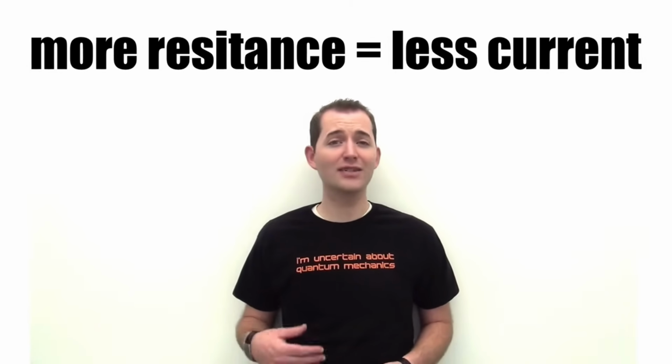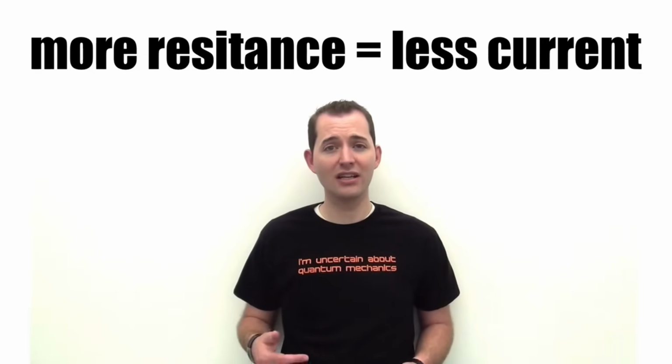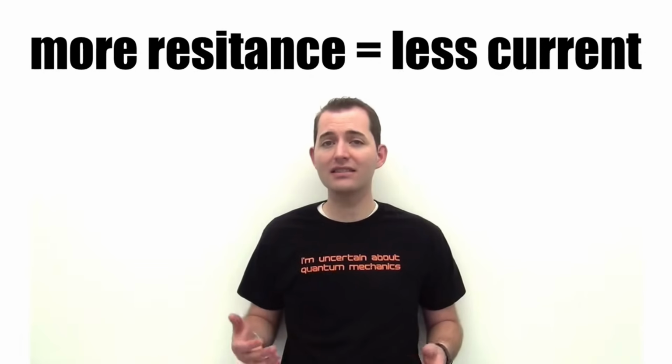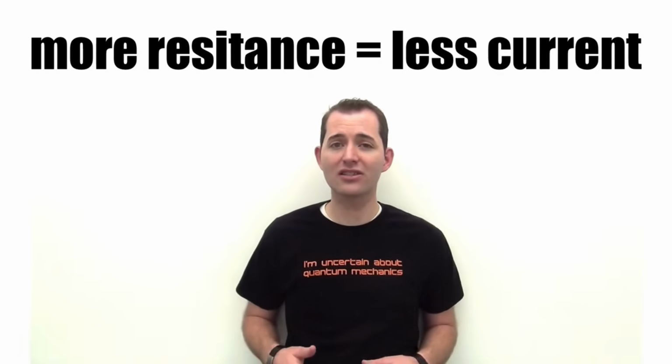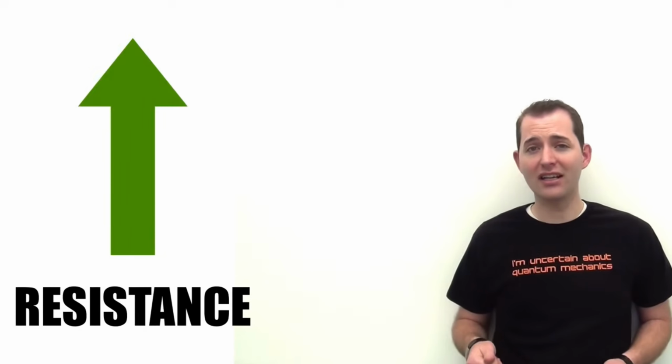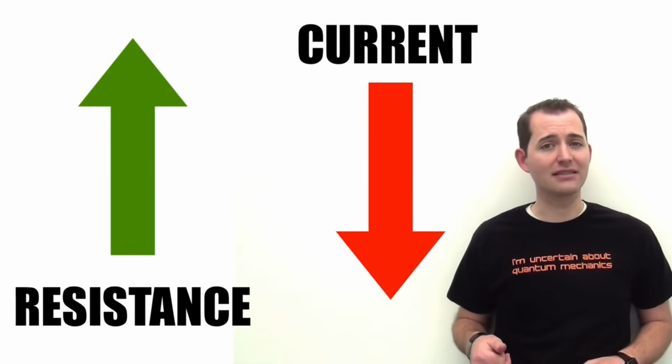The more bulbs we add to that series circuit, the dimmer they all become. This highlights the fact that as we add more bulbs to our circuit, we're increasing the total resistance of that circuit. This causes the total current in our circuit to decrease. This can be stated another way. As the resistance increases in a series circuit, the overall current decreases.